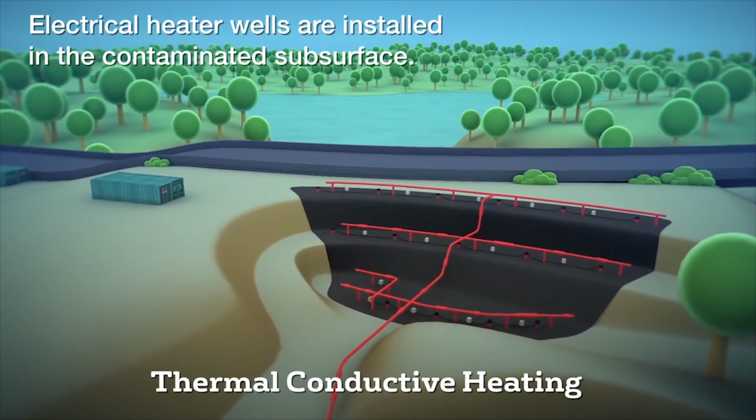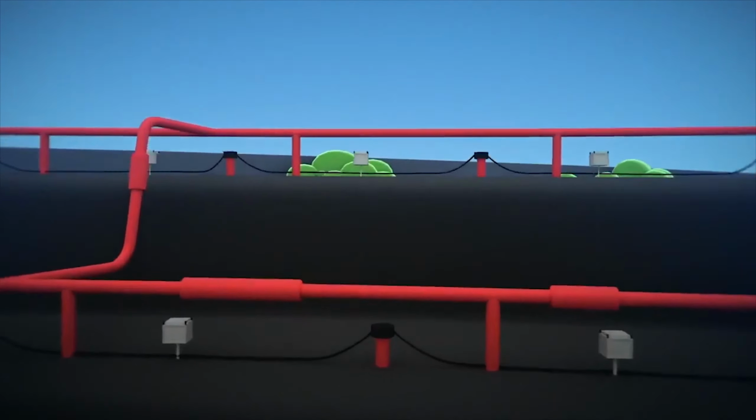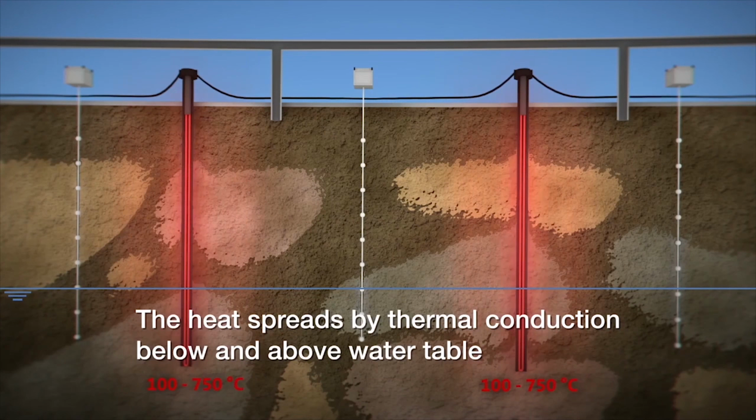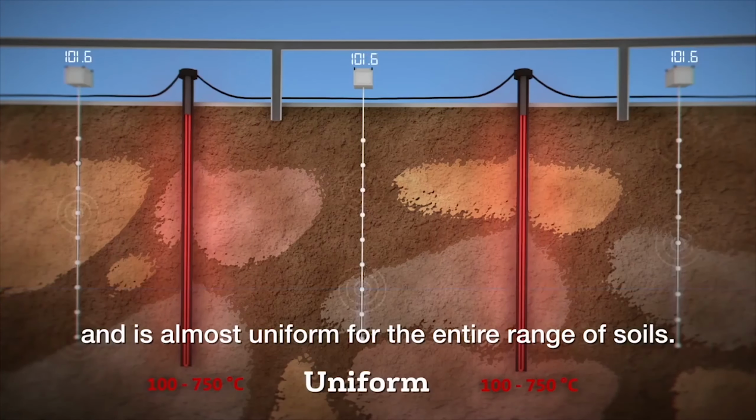Conductive heating. Electrical heater wells are installed in the contaminated subsurface. Only heat is applied to the subsurface using renewable energy. The heat spreads by thermal conduction below and above water table and is almost uniform for the entire range of soils.